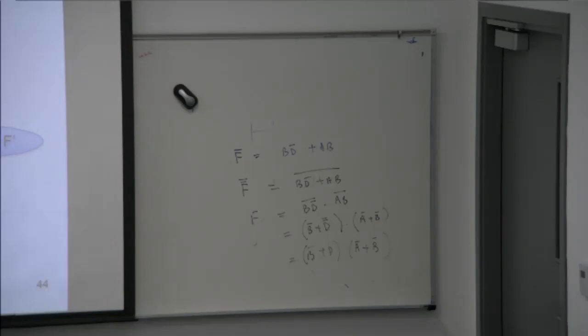So you can do it directly by considering the 0s and combining all zeros, making some groups. If it is 0, directly write it in true form. If it's 1, then write it in complemented form for the POS expression. We know the rules of how to calculate the SOP expression of the POS expression.